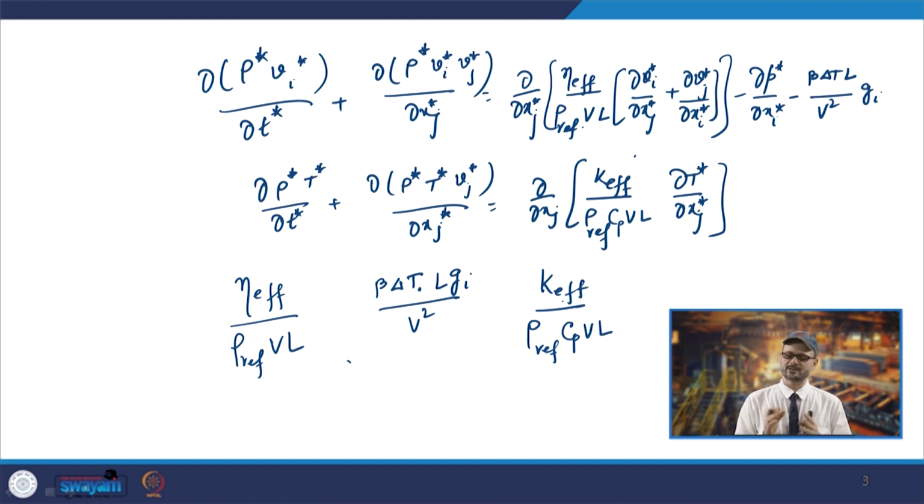So, basically it can be taken as the reciprocal of the product of the turbulent Prandtl number and turbulent Reynolds number. So, basically what you see is that these three numbers come into the picture when we try to study these non-isothermal conditions in the case of the Tundish flow.